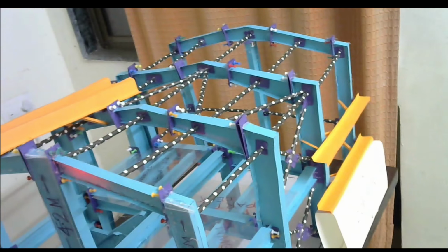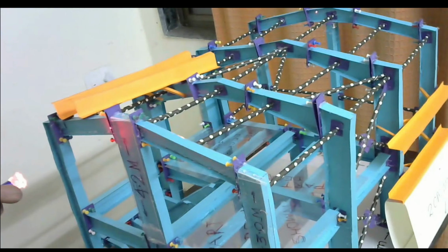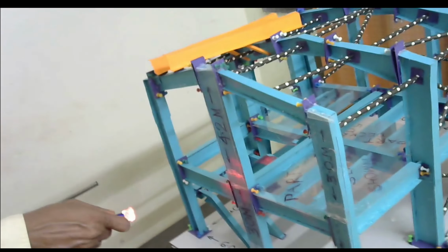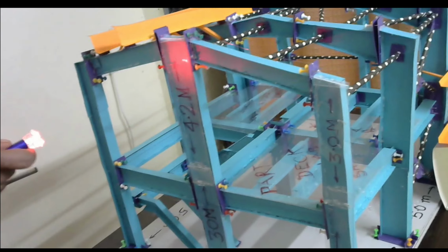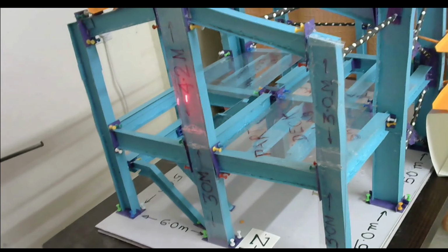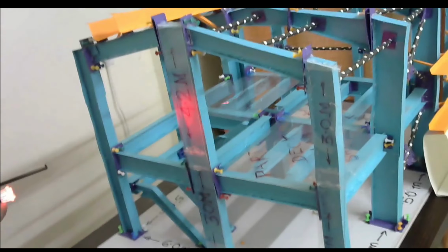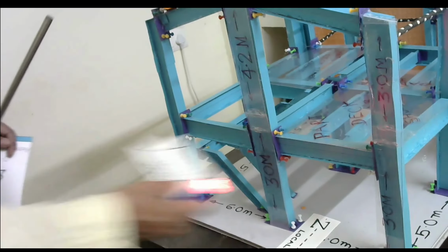Now there is a moment connection here, there is a moment connection here, there is a moment connection here, so there is a torsional resistance here. So the height of this column, center to center distance, is 4.2 meter, so our LX becomes 4.2 meter. Now LY, by the same analogy,